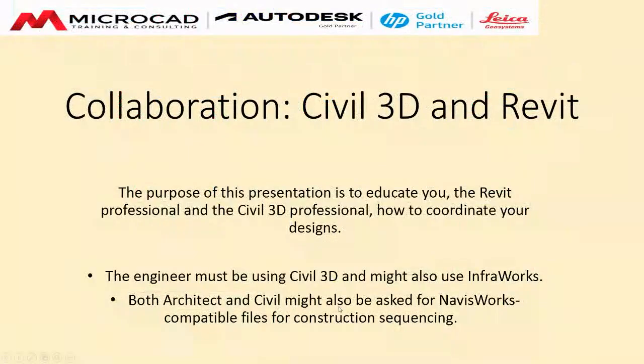That last note, both the architect and the civil might be asked for Navisworks compatible files. This is a file format, a software Navisworks Manage that is used heavily by contractors. And so you can pass them your designs, DWG in the case of the civil engineer, or LandXML for surfaces, as well as Revit files, and then those can be brought together in Navisworks, and those can be used for Navisworks construction sequence animations.